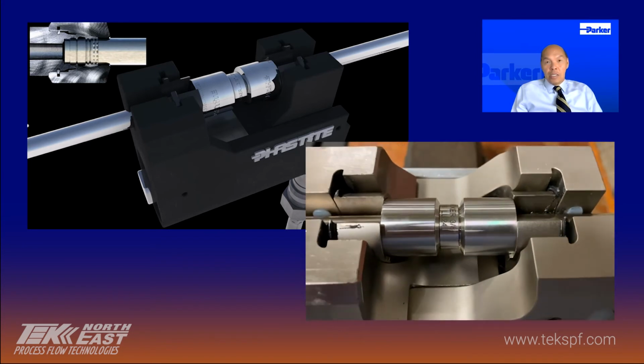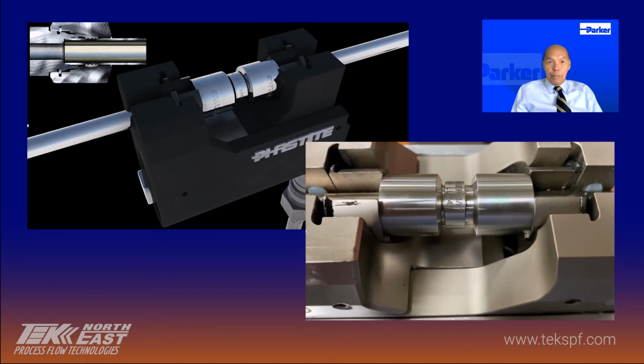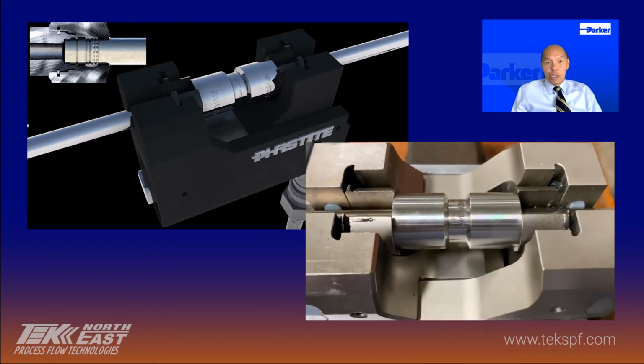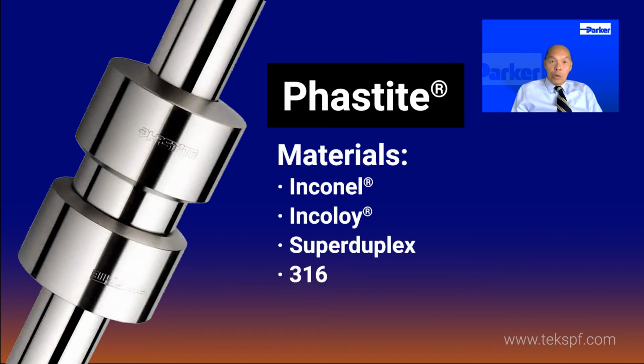The time it takes to make up that fitting is less than 5 minutes, given that you've prepped your tubing prior to installation, meaning you've cut it, deburred it, and made it up correctly. The materials we offer in Phastite are a wide variety, from Inconel, Incoloy, Super Duplex, and 316. And the sizes go from 1/4 to 1 inch.